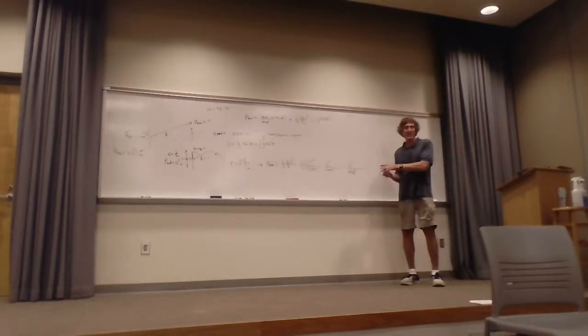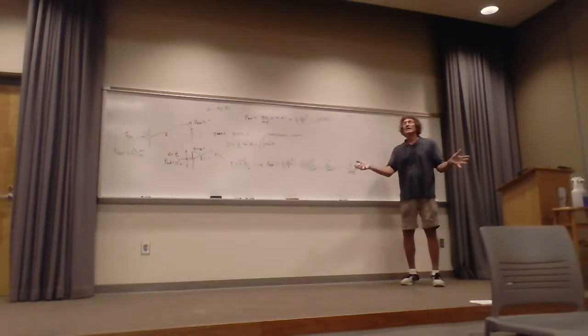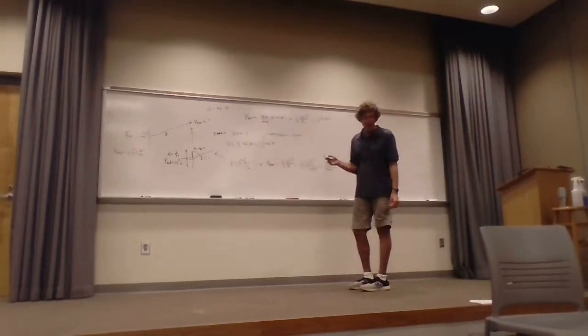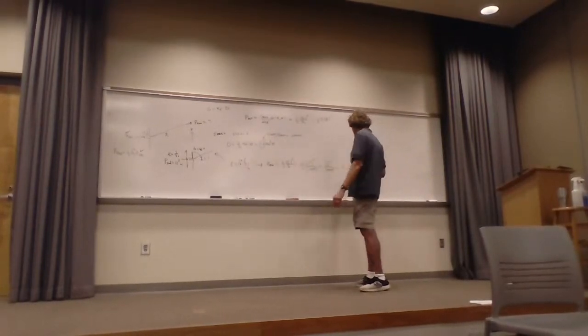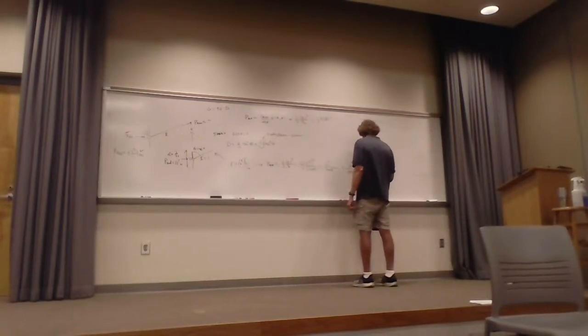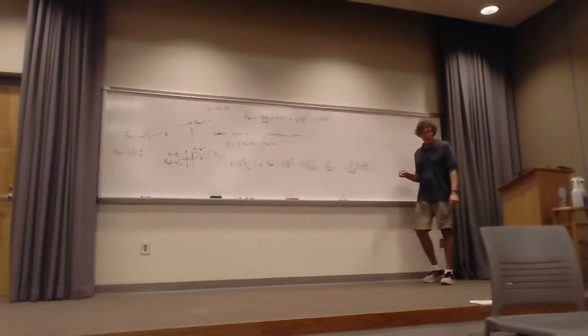This is isotropic, right? There is no focusing. I have to multiply it by the gain, right? Directivity, we're going to assume directivity and gain are the same. It's 100%. So the directivity would be 3/2 or 1.5 times sine squared of theta, correct? You all agree with that?